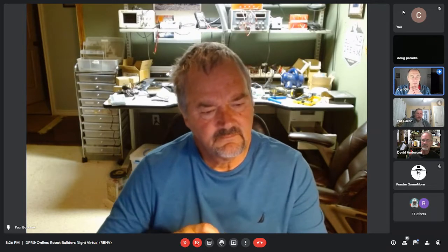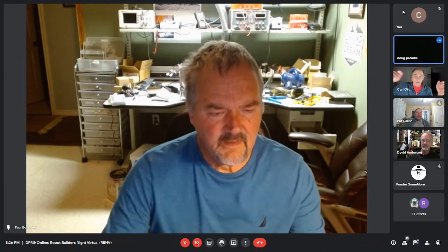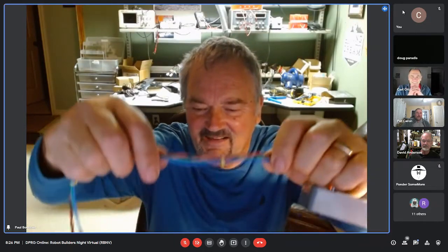So what would you twist, like SDA and SCL, with? I would just twist them all together. So like what we would do back when I worked in the defense world at TI, and we had to make twisted cable, is we would just take however many wires we had and lock one end in a vise and the other end in a power drill. Yeah, well, I did that.